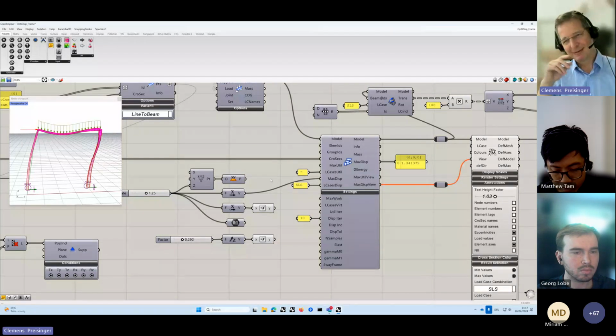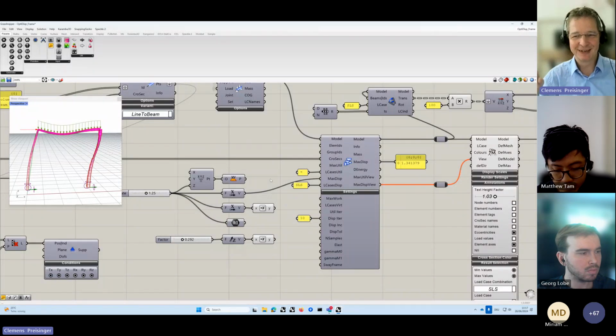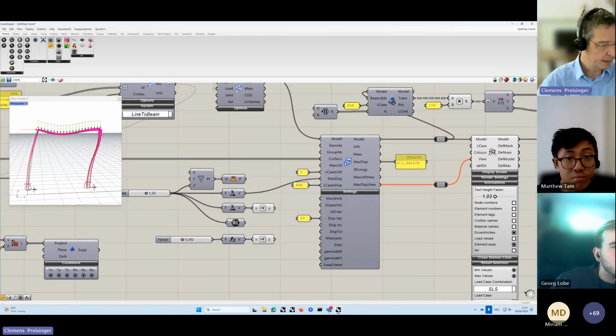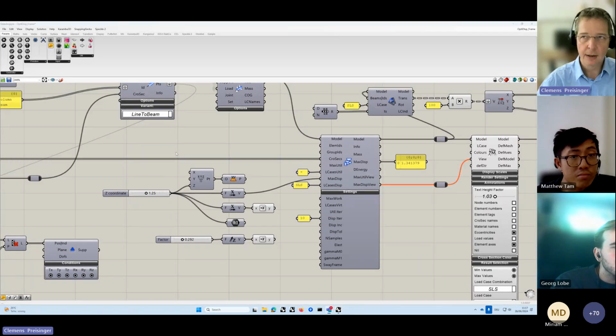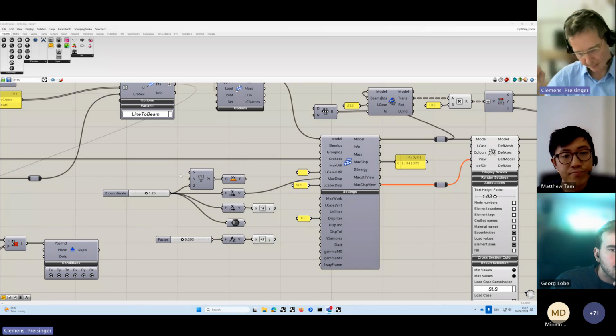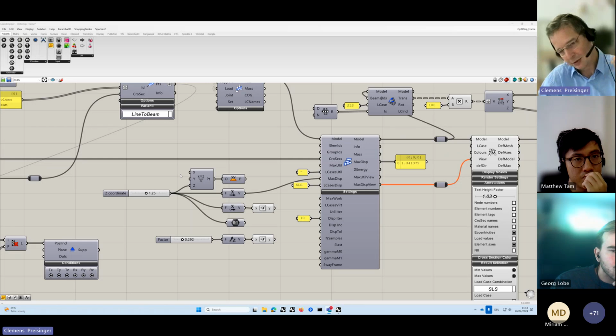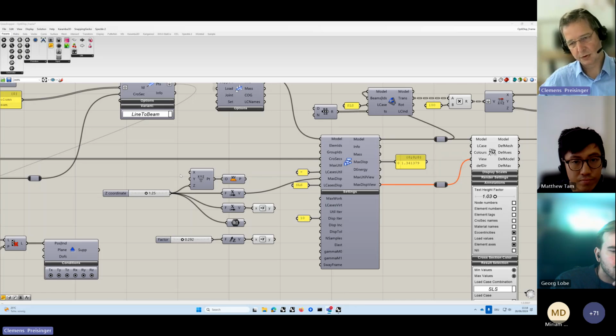And the major improvement here is now that this displacement optimizer is based on the principle of virtual forces. This means that the different parts of the structure which are too weak can be strengthened, but only in those regions which are actually too weak, and not as it was the case in the previous version of Karamba, that all the structure was made stronger or less strong.